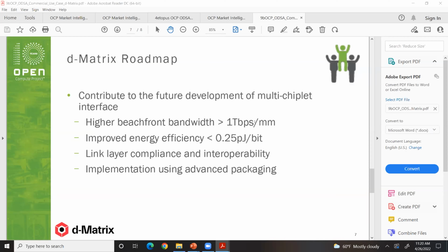This question is very open-ended because it depends upon the limitations on the package size and also what is your parent die size. You can have a whole tile of designs on chiplets by itself. But we have seen in a commercial deployment 7 to 8 chiplets hooked onto a parent die. That doesn't set the maximum limit, but this is what we have seen so far.